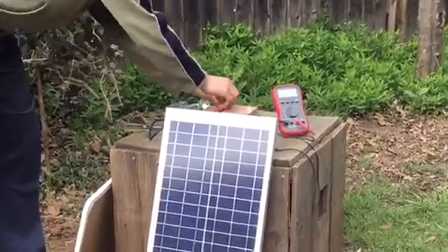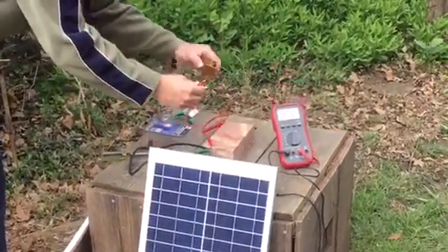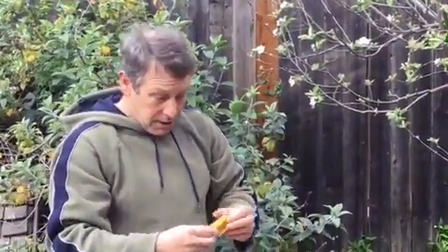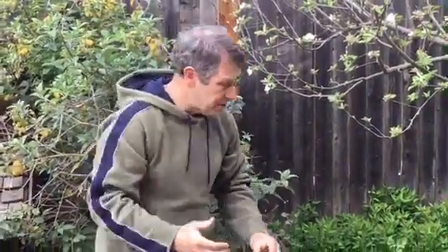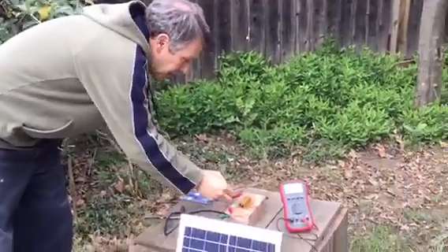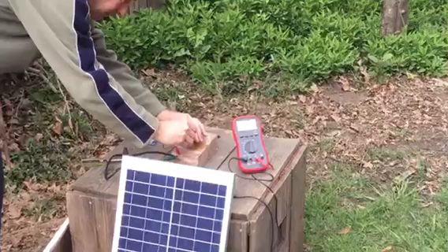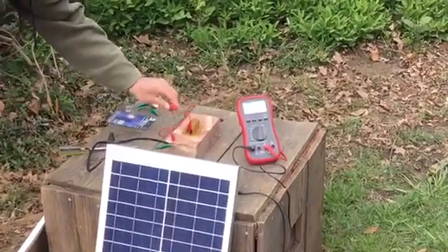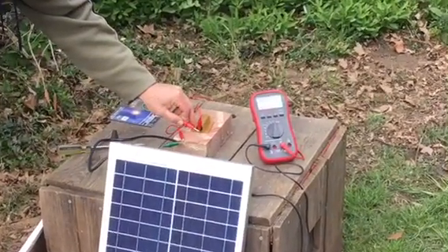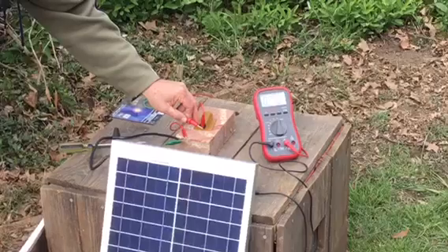What I'm going to end up doing is I got this resistor here. We talked about that last time we met. That's a 5 ohm resistor. It's a pretty low resistance actually. And I'm going to go ahead and hook that up. So now instead, pardon me, we've got 5 ohms going through there. Okay, I touch here and I got short circuit. And it looks like we're up to about 0.3 amps.